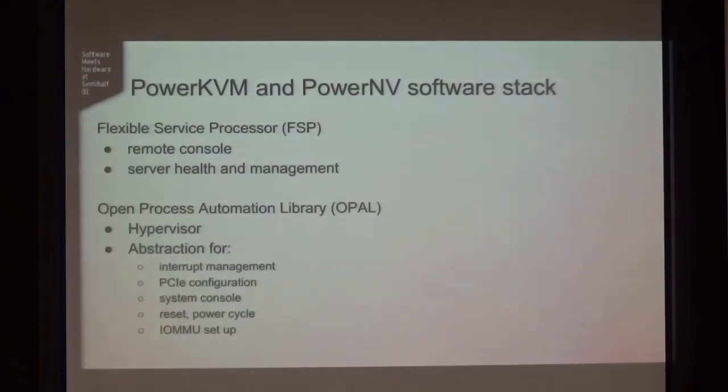This is what I already said. The FSP is not very interesting, but the OPAL library, the hypervisor which is working on the PowerPC POWER8, is required for managing almost everything. If we want to configure the interrupt, configure PCIe, have a system console, for example, we need to perform a hypervisor call up to the OPAL to ask it to do something for us. So this is some architecture which IBM relies on, and we can't avoid using OPAL at all.